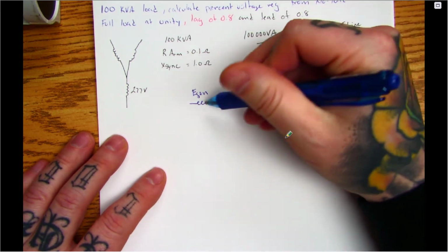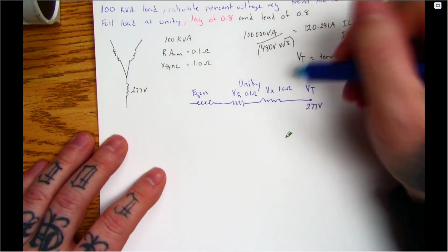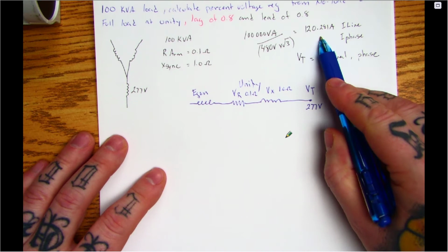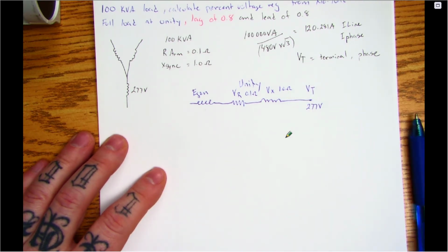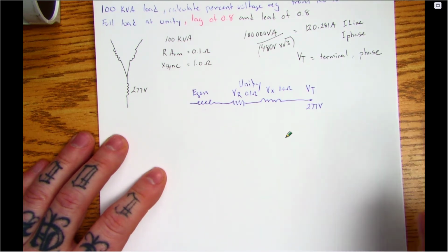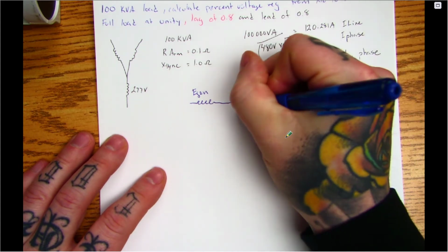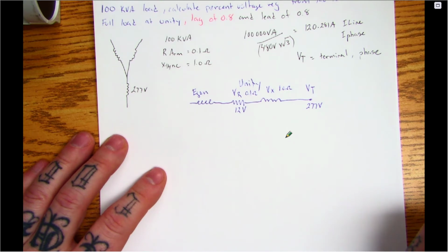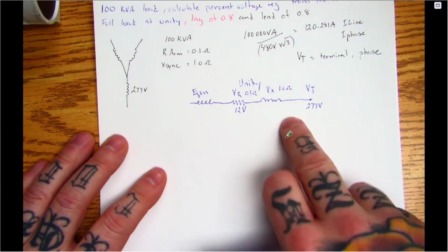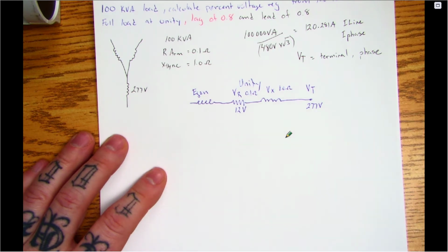So I want to find out what the volt drops are across these. If I use this current, 120.281 times 0.1, I should get that 12. So I'm just going to say this is 12 volts. Okay, so that's my volt drop there. I might just round to make life easier here, just for this comparison, but again, in our bank, go to 3 decimals.